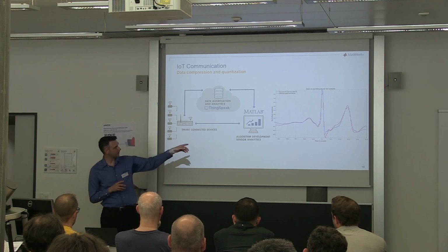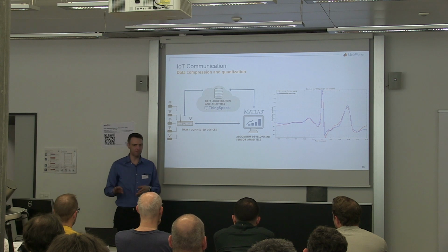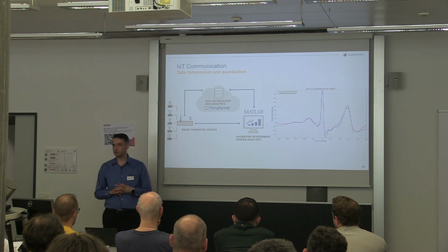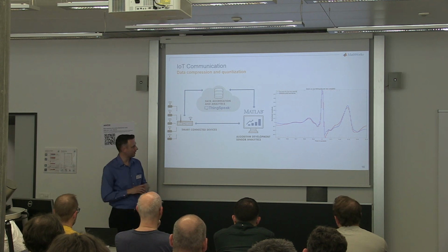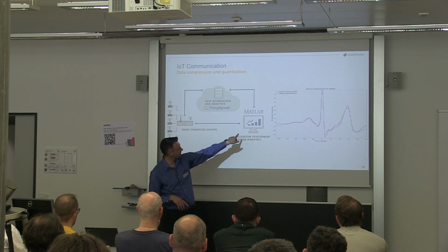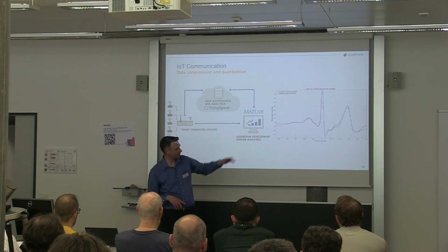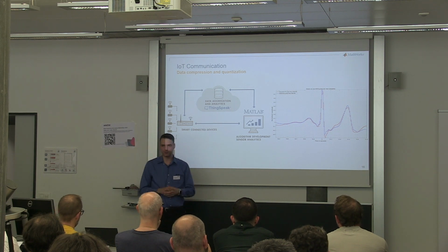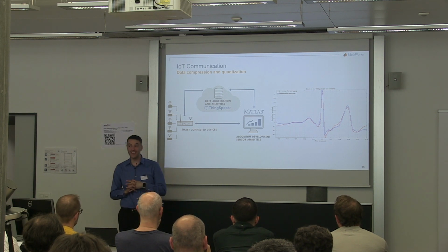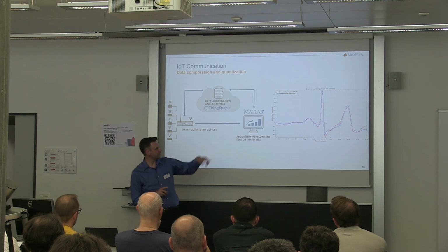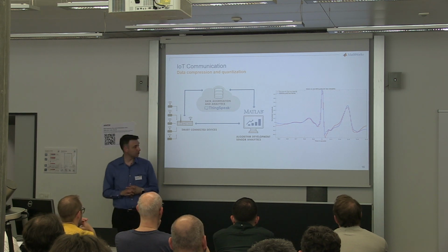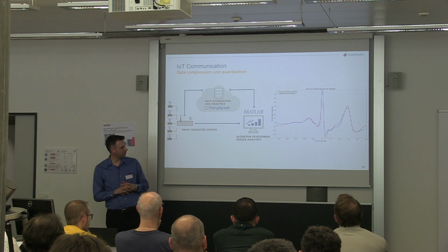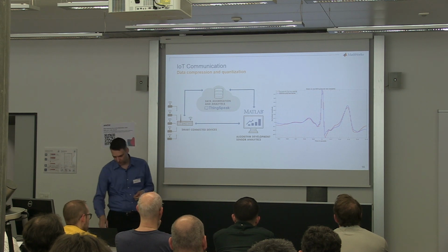And here you can see that the data have been compressed by a factor of 125 or something like that. It may seem big, but at the end, when we compare both signals, the blue one, which is the reference done with double precision floating point, and the red one that was compressed down to a uint8, the difference is not that big. Both signals have the same shape, they follow the same rules, so this works pretty well.